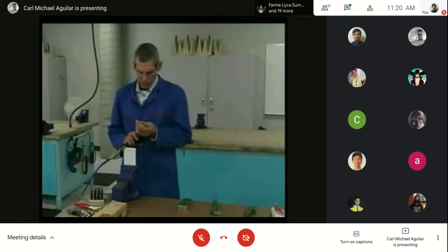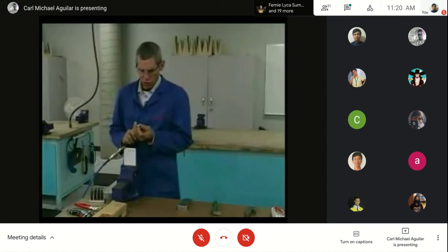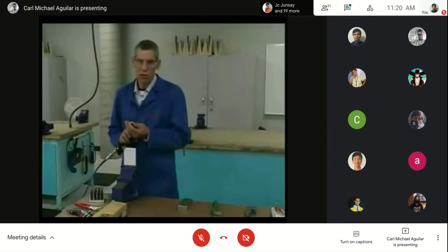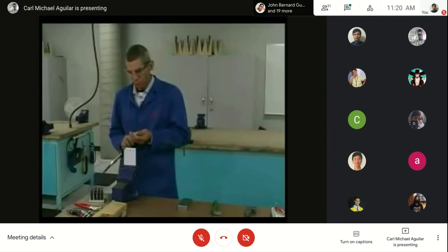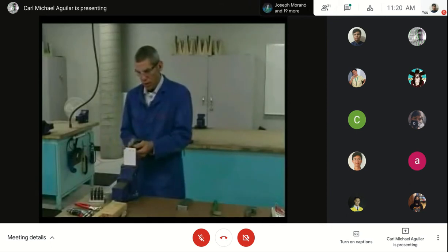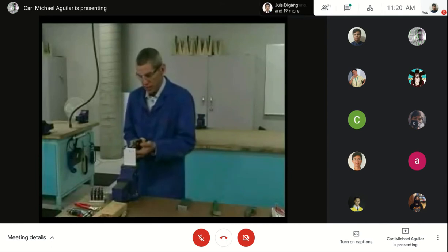Looking at the rivet set, I want to make sure that it is free of all foreign material inside there. There's no masking tape or wood fibers in there, and that it's not damaged by file damage or other marks on the rivet set, so that I've got a good serviceable rivet set. I place the rivet into the hole. I'm going to be putting the rivet gun onto the manufactured head side here.